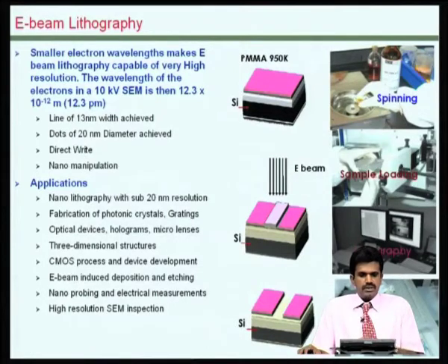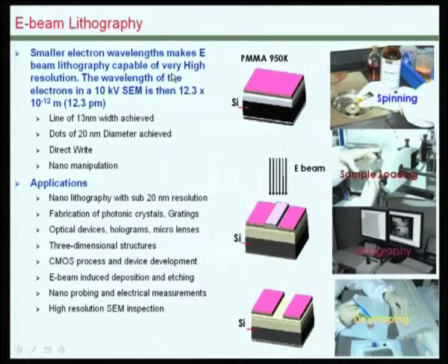What you see here is an example of an e-beam lithography in our facility for patterning very small dimension geometries, such as dots of several tens of nanometers or lines of few nanometers width, and this is possible by using PMMA resist and using exposure using an electron beam approach rather than the UV light, as you see in the previous examples.